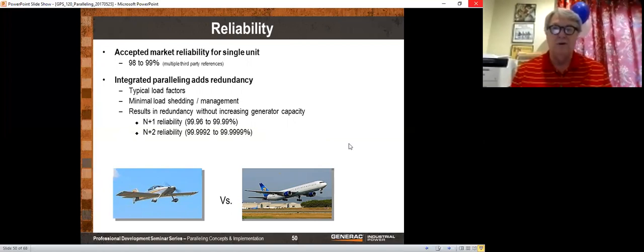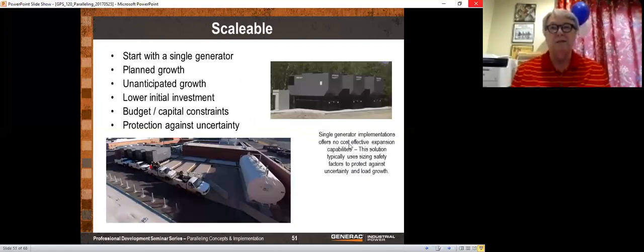So we actually have N+2 redundancy. And what's not to like about that? There are just so many advantages that you would not have gotten with the 2 megawatt generator. And this is fairly typical. People buy an MPS system, which stands for modular power system, in order to get the reliability and so on. They end up with redundancy, even though they didn't buy it.